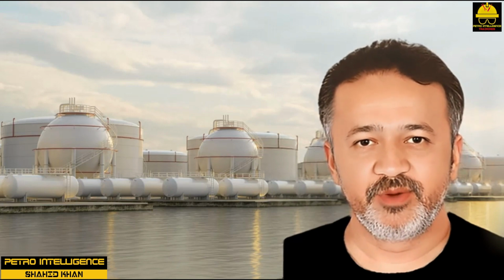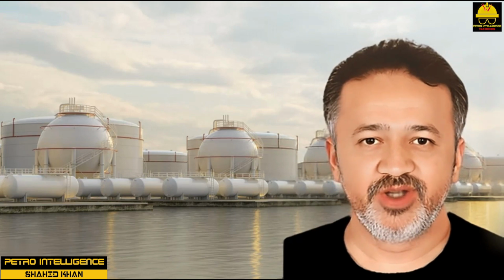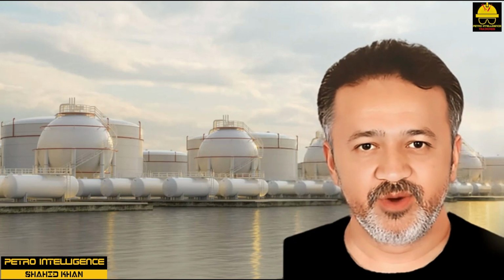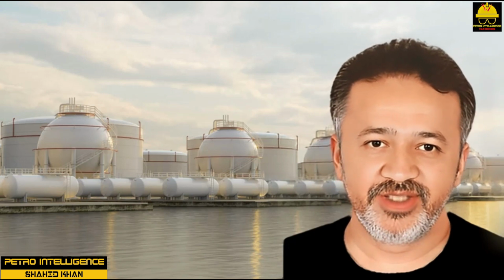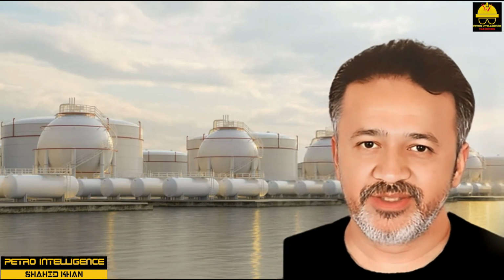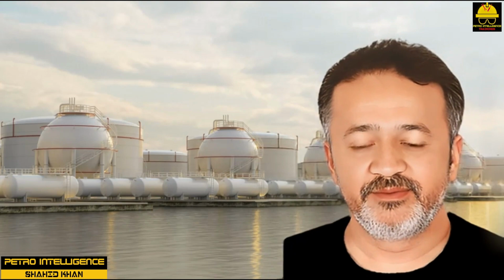Blocking in equipment unprotected by relief valves, unofficially increasing the relief valve set pressure, and blocking in cooling water in exchangers while in service are only several possibilities of creating hazardous conditions in the unit. The operator should be aware that such unsafe practices can exceed design conditions and may cause failure.